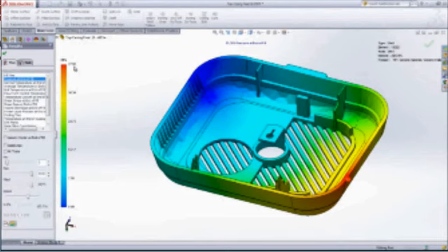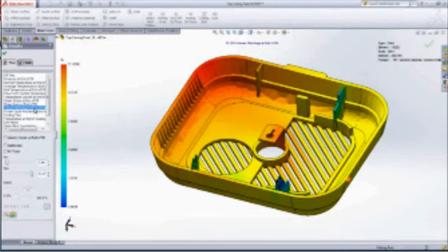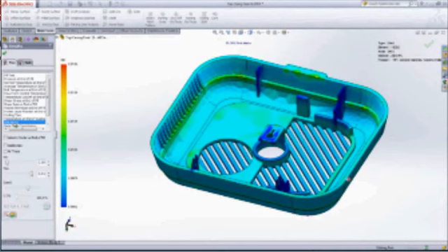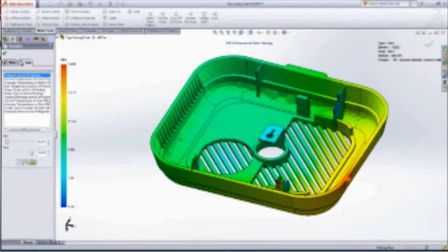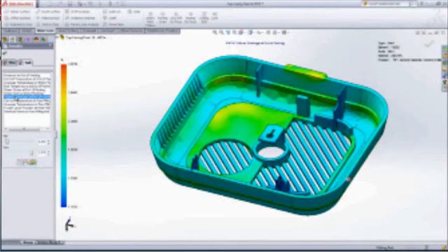part. Satisfied with this design and having overcome most of our initial challenges, we can now also look at the volumetric shrinkage. All these plastic materials shrink. That's why the volumetric shrinkage at the end of packing is more important. By changing packing pressure and time, we can actually affect what our volumetric shrinkage is. Overall, we've reduced the volumetric shrinkage from the 10-12% range down to 1-2% range after packing. Also, we have a much more uniform distribution with no significant differences from one end to the other, so that's highly unlikely that the part will warp or deform out of shape when it comes out of the mold.